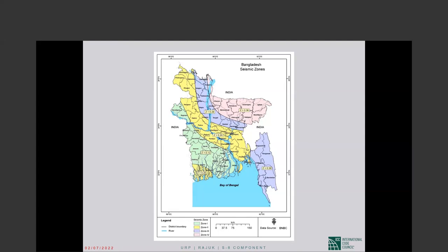So those who want to play it safe design a building that can withstand the design earthquake of the code with the infill intact. And they also design a building that can withstand the design earthquake with the infill all gone. Both ways, the structure should be able to withstand the earthquake. So the specific answer is the infill initially contributes to stiffness, but the contribution goes away when the infill is damaged in an earthquake.